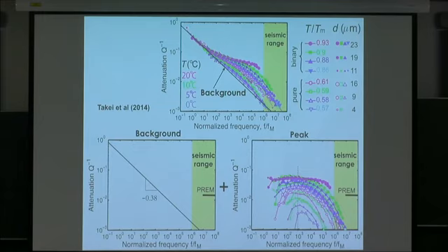The homologous temperature is higher for the binary samples. So, the variation is quite systematic. As shown by these pink arrows, the center frequency normalized to the Maxwell frequency is constant for all data, and the amplitude and width of the peak increase with increasing homologous temperature and increasing grain size.